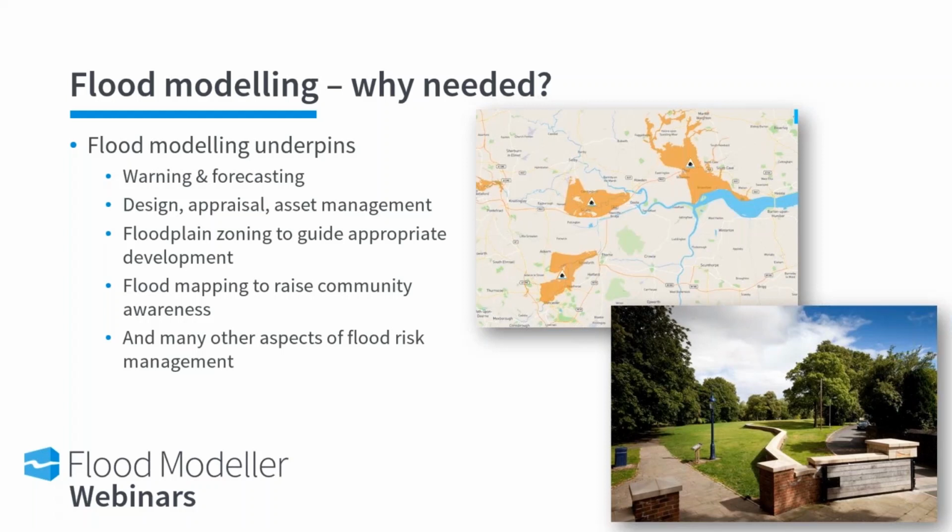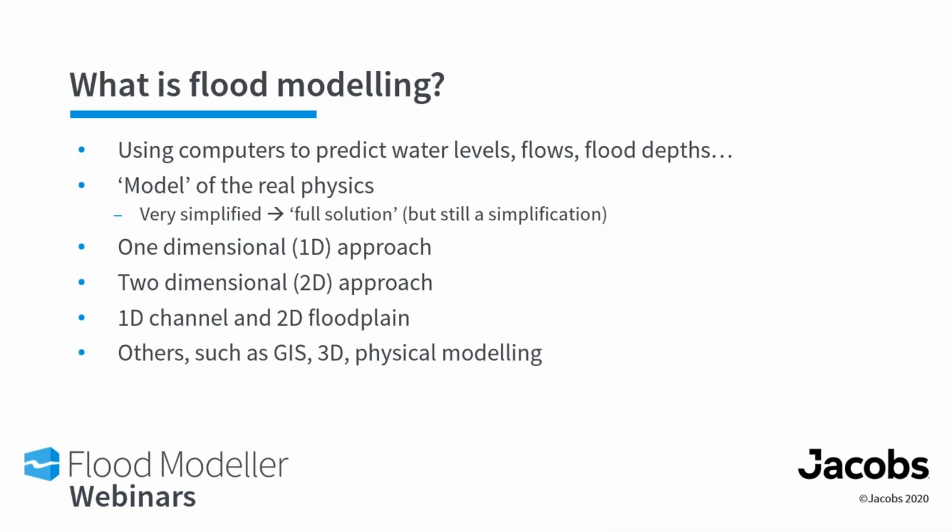Modelling is used to understand the pros and cons of different investment levels, as an example of one of these other areas. So what is flood modelling? Well, essentially, nowadays it involves using computers to predict what the water levels and flows in the channel system, or on whatever network you're looking at, and the flood depths on the floodplain are, for a range of different scenarios, if you like, which can be different amounts of rainfall or different extreme tides, looking both now and into the future with climate change, and then with different setups on the floodplain, with and without interventions, with and without development.